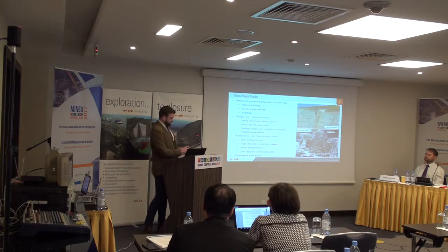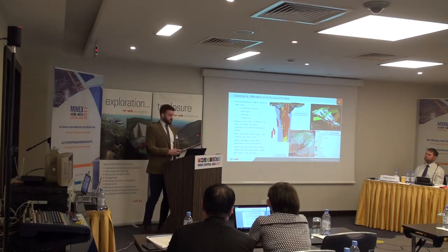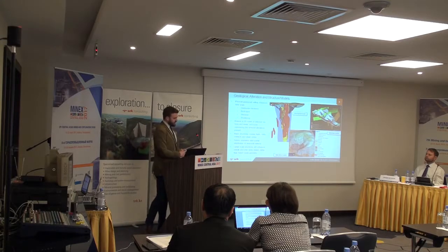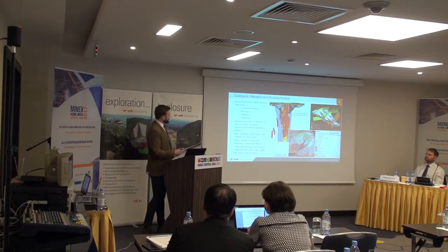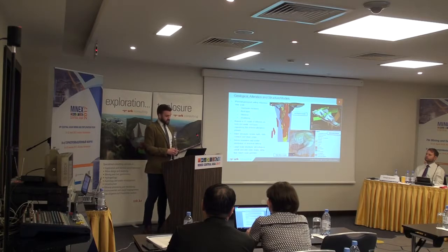So I said these are some of the geological models, the alteration model and the structural model, and really you need to understand these for your geotechnical model, and you have to have a good understanding of the different rock types, the geometry of the resource, and any weathering that may affect the rock mass. Another important element to understanding is the alteration model, because that can have a detrimental impact on your rock mass and subsequently your pit slope design.